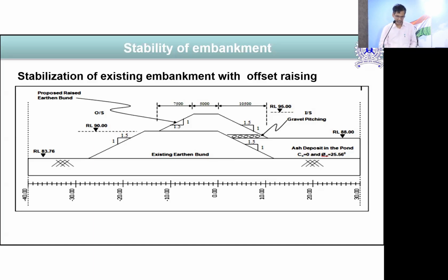I forgot to bring that picture maybe, because in one case the slurry on which I am providing the dike is not sufficiently dry, or the strength was found to be less. In that case, people are now putting in PVD drains and stone columns.